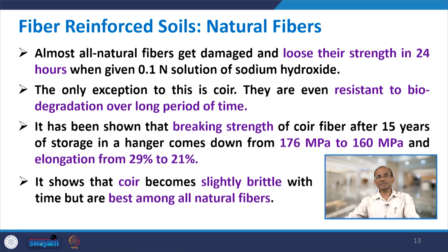Almost all natural fibers get damaged and lose their strength within 24 hours when given 0.1 normal solution of sodium hydroxide. The only exception to this is coir. So, coir does not have this problem. It is even resistant to biodegradation over a long period of time. It has been shown that the breaking strength of coir fiber after 15 years of storage in a hangar comes down from only 165 MPa to 160 MPa.